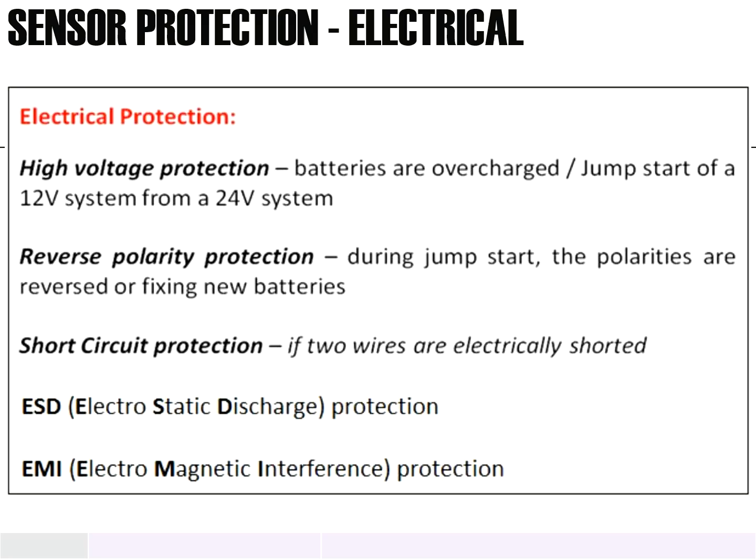Therefore, appropriate electrical protection is required for sensors and their associated circuits. The purpose of the electrical protection is to ensure reliable sensor operation and protect the sensor and electronic control systems against undesirable electrical conditions. This is especially important in automotive applications because sensors are connected directly or indirectly to the electronic control unit, that is the ECM or ECU.